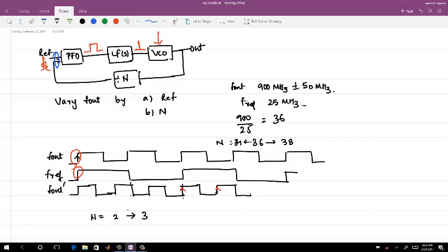The ideal goal is, when I change my divider ratio, if I correct for the phase error here and if I correct here, the ideal transfer function is all pass. That's the ideal case if you take all the loop gain into account. And if it is all pass, then ideally you do not have any delay.